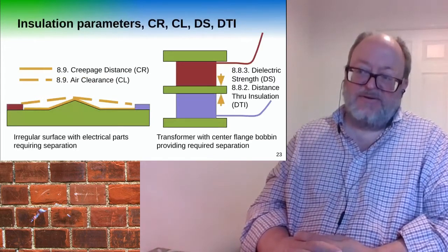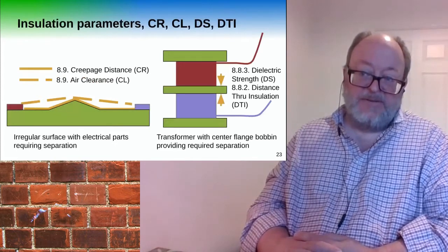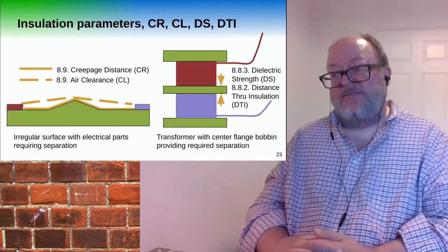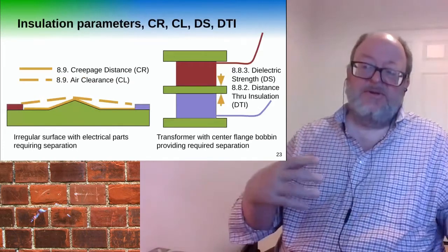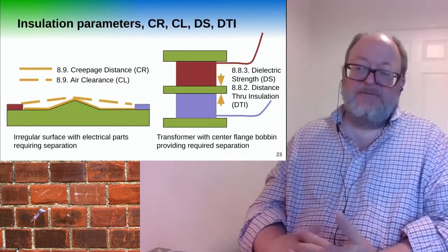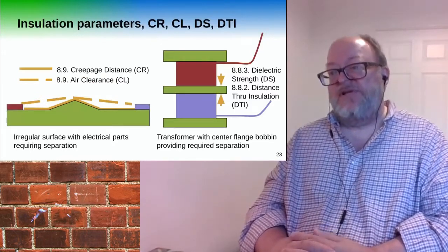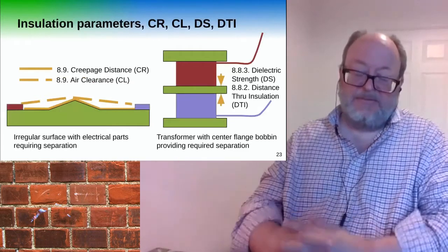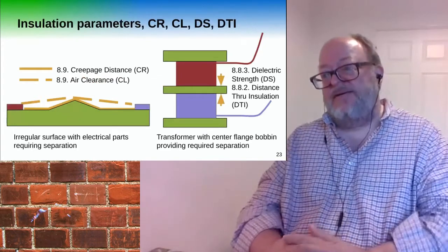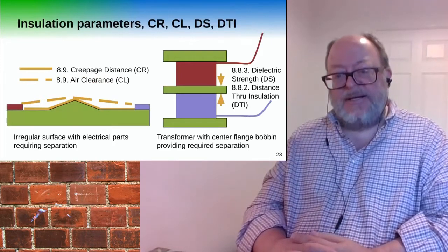Air clearance is the shortest path through air, and that could be weakened by repetitive peaks as well as transients on our mains. Lightning, switchgear out on our transmission comes into our buildings. For example, with 240 volt mains, we presume that it's common to have 2500 volt peaks. And it could be higher, but that would hopefully be more rare. But the common general peak we'd want to worry about is the 2500.